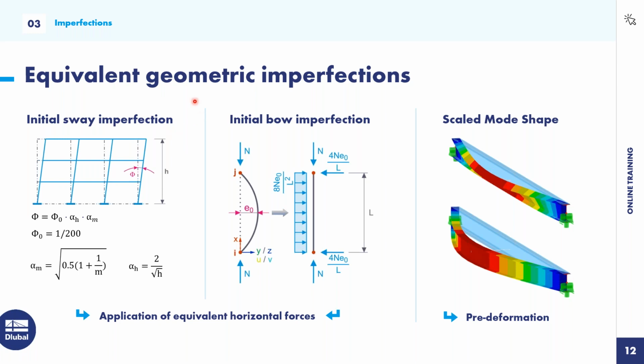When I manufacture some steel profiles, for example hot rolled sections, it can be possible that some internal stresses appear, and these kinds of effects need to be considered, because what we do the whole time in the structural analysis programs is to consider ideal models, but the reality is not ideal. So in order to consider these effects, we have to apply imperfections.